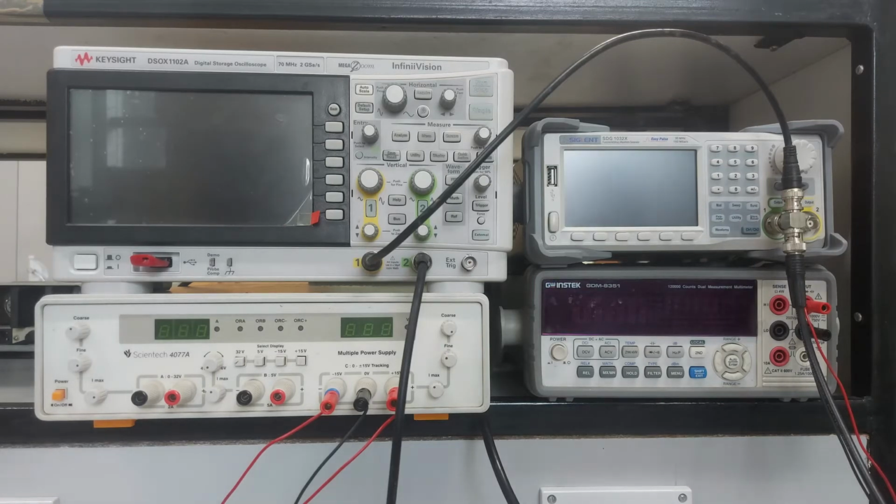As I said, it has two inputs. One is the inverting input and another one is the non-inverting input. Because it is a differential amplifier, obviously there should be a difference. Amplification should be the difference of the two inputs. One will give you the output as an inverted version of the input, that is why it is called the inverting input. And the other is the non-inverting input, because if you give the input at the non-inverting input, you will get the output non-inverted, I mean, you will get the same phase output.